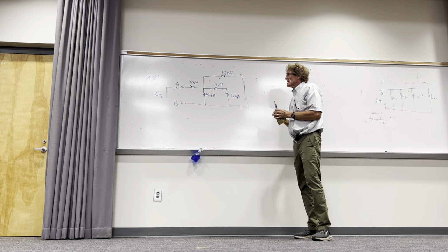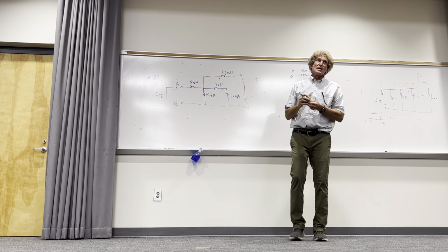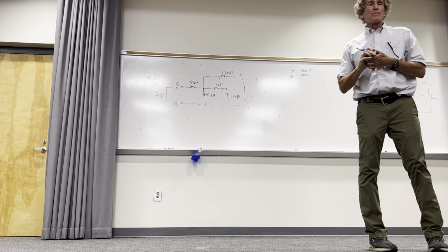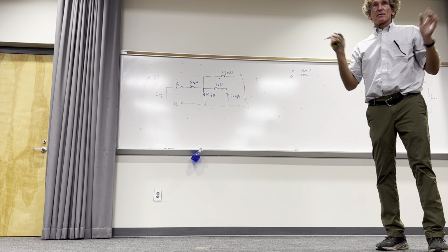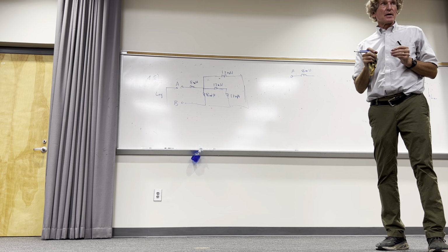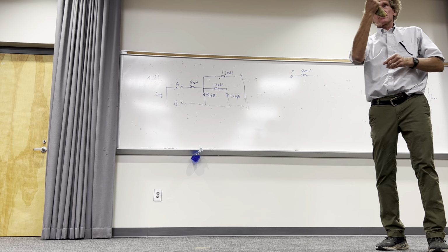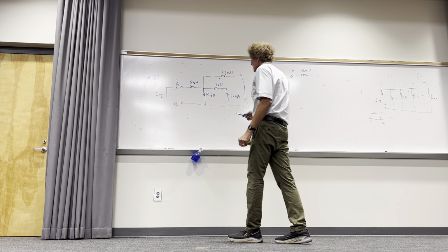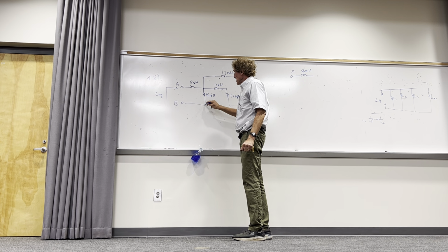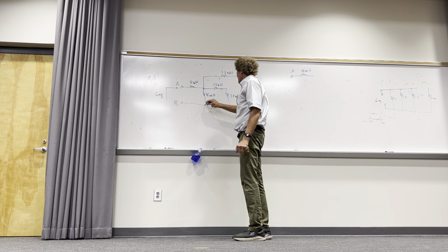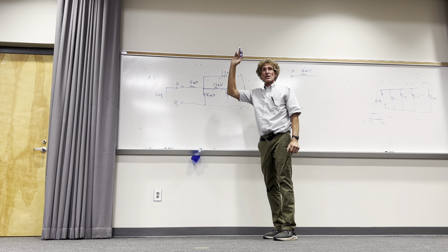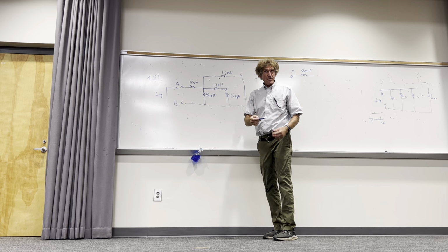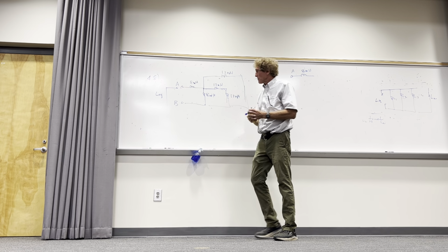What next? Take a look for a second. Now I could get the colored markers out, but just take a look. Remember, topology means nothing. It's the electrical connections, right? Doesn't matter if the inductor's up this way, over that way, down this way. It's electrically how they're connected. Now at this point, from here to here is 8 millihenries. Do you agree? When you look at that, what about these two? Series? How many see it? What can I replace them with? 24. Do you agree with that? All right, I'm going to do that.